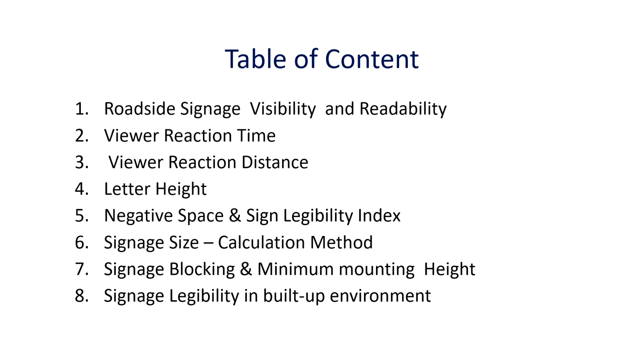What we will be studying in this is roadside signages, visibility and readability, viewer reaction time, viewer reaction distance, letter height, how we decide them, navigating spaces, signage legibility index, how to decide the signage size, what are the calculation methods, signage blocking and maintaining mounting height, signage legibility in built environment.